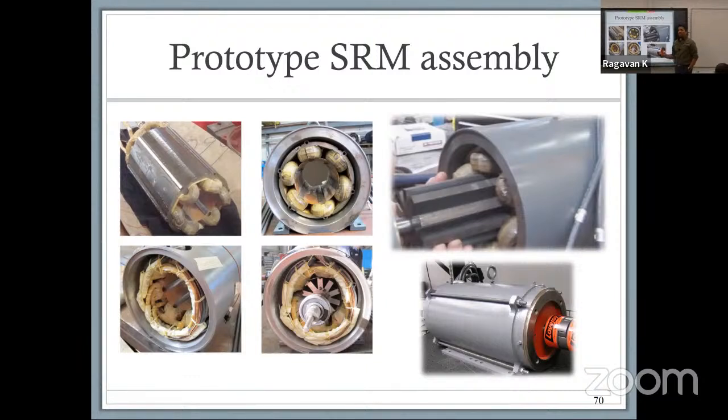The challenge we faced was that because we did not plan out the motor entirely, we ended up with a housing that fit, but we actually had a gap in the front and back a little bit, which means for this specific motor, our acoustic noise measurements would not be practical because you now have created an acoustic chamber within the housing that will not exist in the real application. So that was a little bit of a learning moment for us when we went about the housing design.